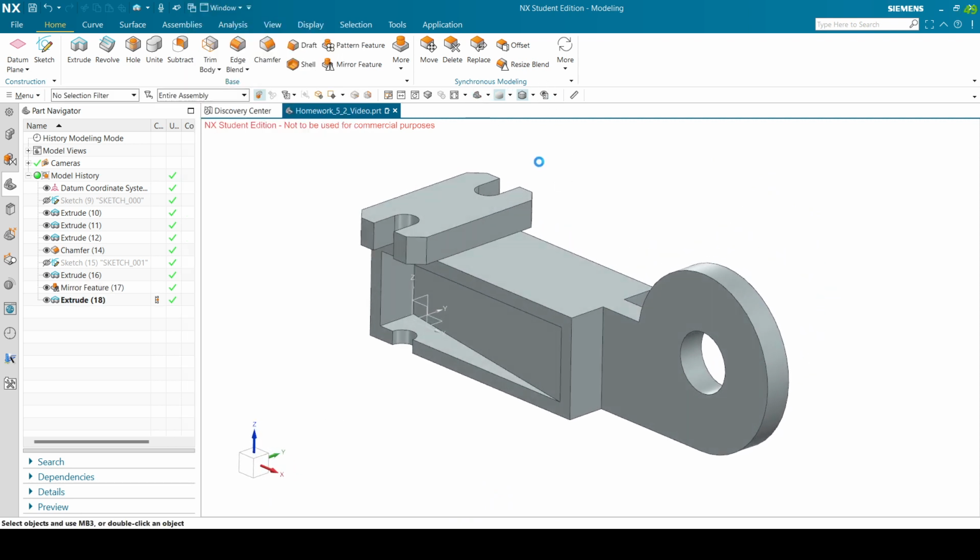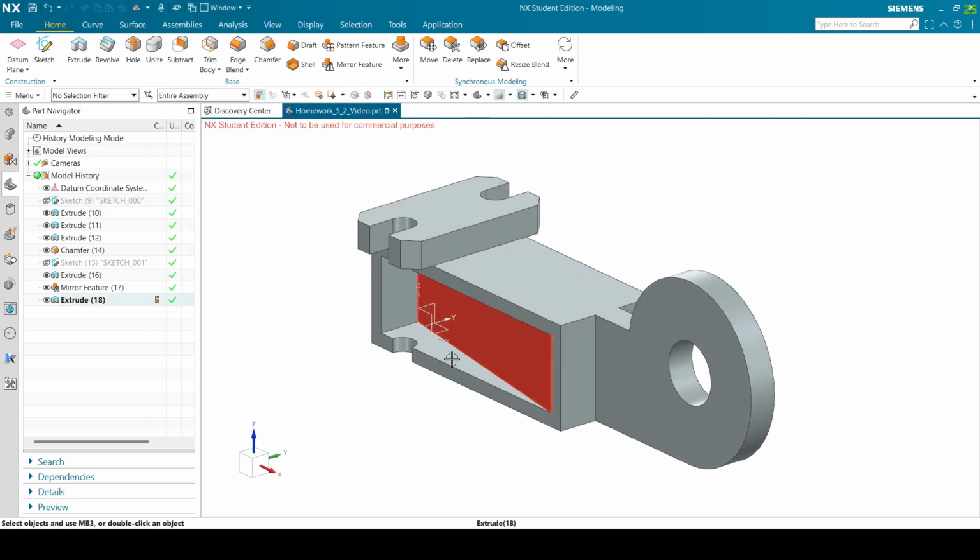As easy as that. No extra sketches that you cut out from a thing, and now if that changes, you need to go and edit the sketch and so on. Just a simple draft in your extrude. You can also draft after the fact using the drafting feature over here, but if you can do it in one feature, then do it in one feature, and then you save yourself the hassle. So yeah, and that's the entire part.